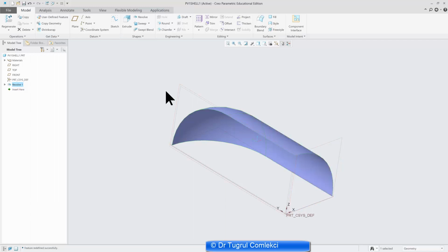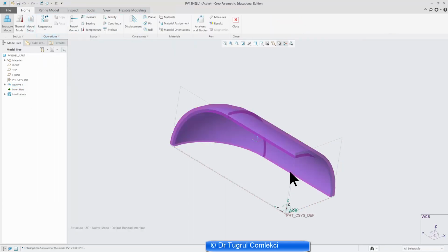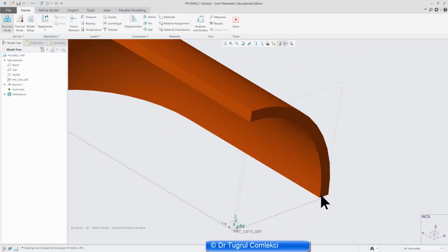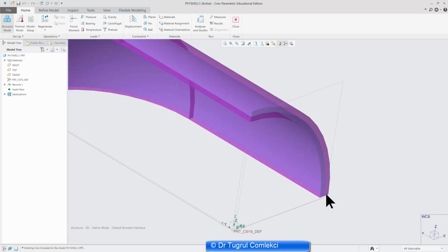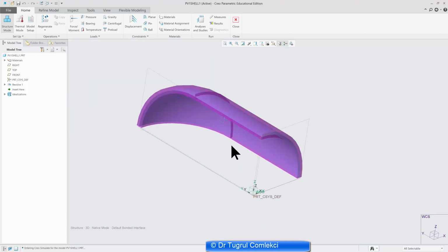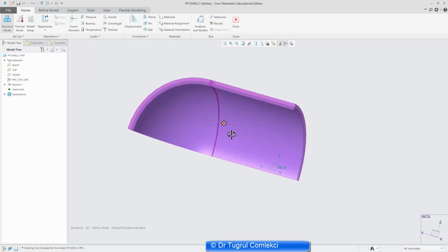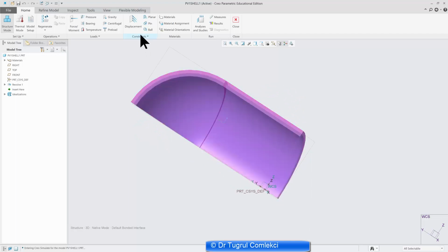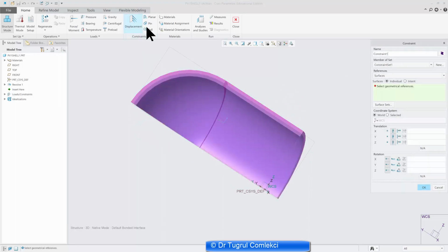105 millimeters. And if I now go to Simulate, I can see that my shell definition, the internal radius of the shell will start from 100, and the thickness is now defined as 10, so outside radius is going to be 110. Now we can apply some boundary conditions on these before we solve this. The displacement boundary conditions can be applied on edges of the shell.